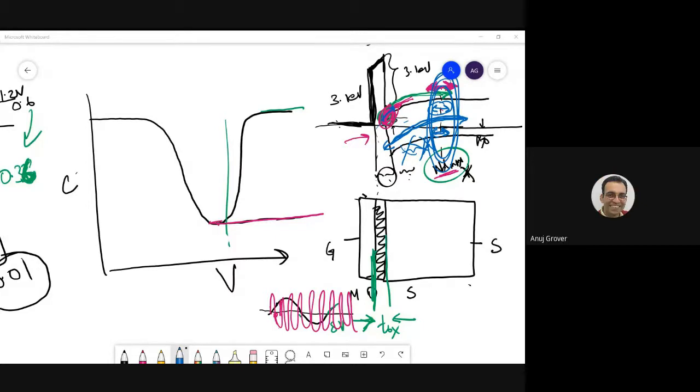See, the x axis that you see is your V bias. And this thing that I showed over here is your V small signal. So this could be 1 volt, and this could be just 20 millivolts. So we're talking about just a 20 millivolt fluctuation.